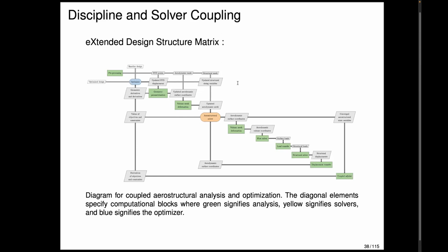Now, this case setup is passed into the aerostructural solver. That's this somewhat circular block here in orange. And this is what's responsible for converging the aerodynamic solver with the structural solver. So that's what's going to do the two-way coupling.